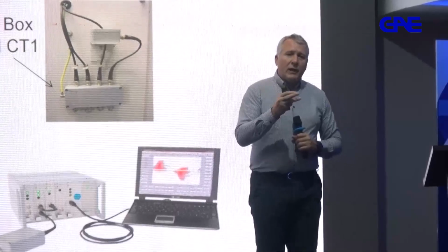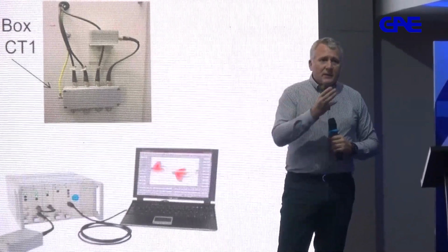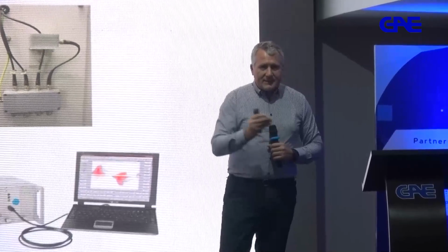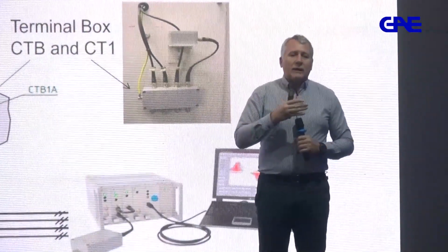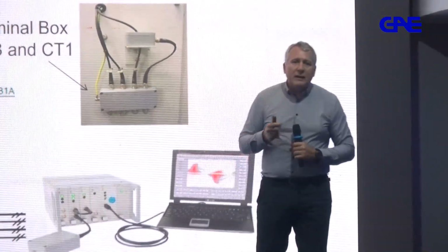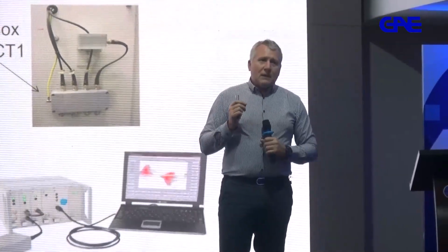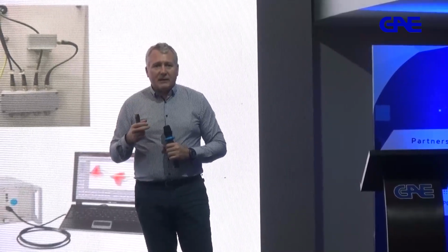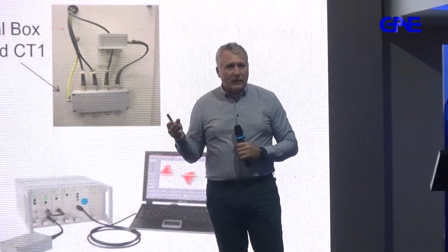maybe it's a good idea to continue to test for partial discharge as time goes by, because then, same as for a person, you have some blood analysis done at this time, another set done at this time, another set done later. So you can look at the trends, and those trends are going to give you a very important piece of information that will give you more or less the action that you need to take in terms of doing condition-based maintenance.